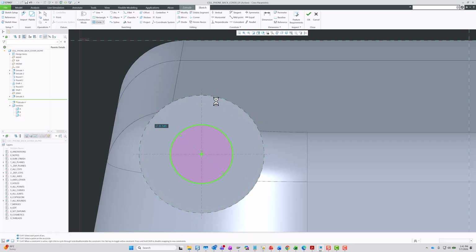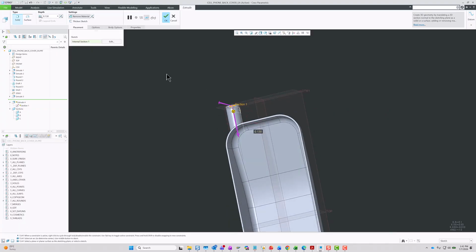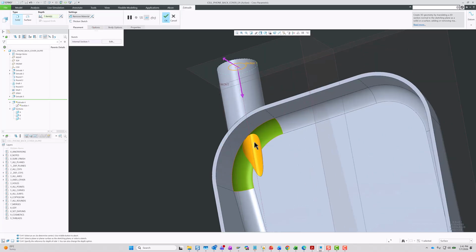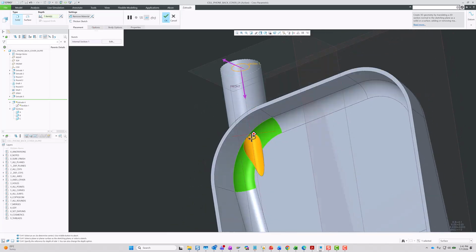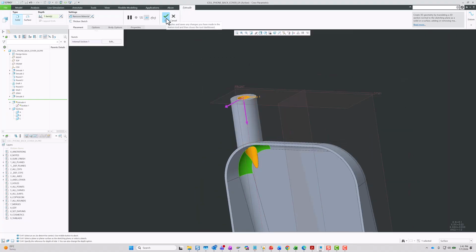All right. So right mouse button and update the diameter of this new hole to 0.13. And the hole depth will be defined using this tool, through until, and you can select this surface. So as you can see, the hole will be cut until they touch this surface. All right, so let's click OK.